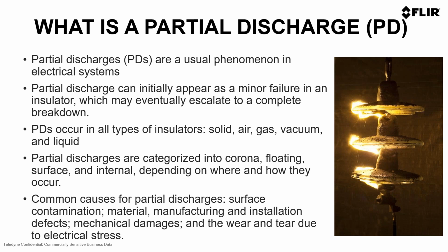For example, we are taking into consideration an insulator. PDs can occur in different types of media: solid, air, gas, vacuum, or liquid. And from this, they are also categorized. They are categorized mainly in the literature as corona, floating, surface, and internal, depending on where and how they occur.